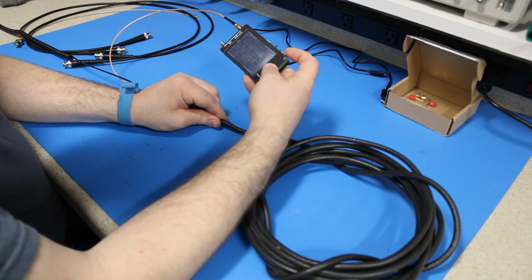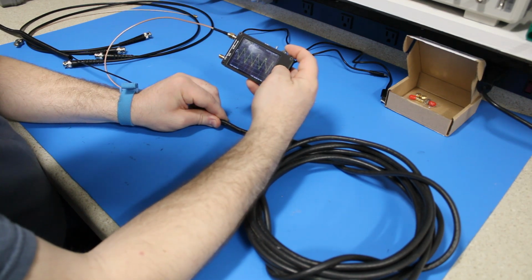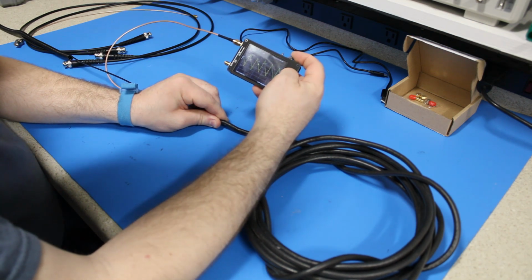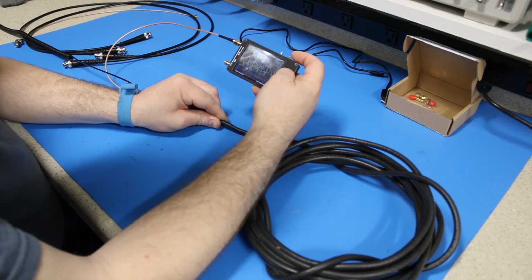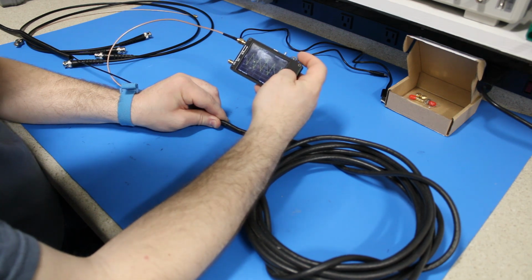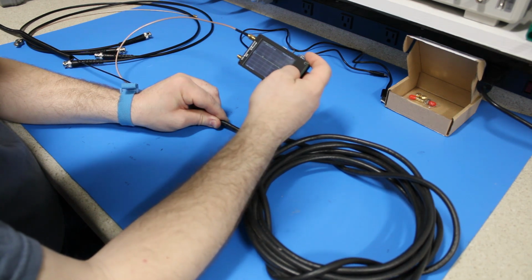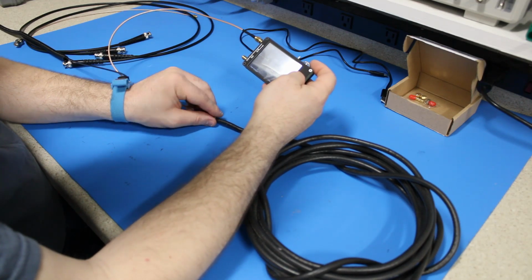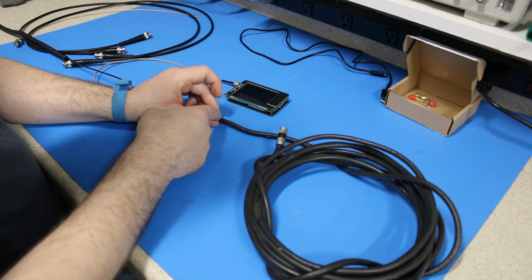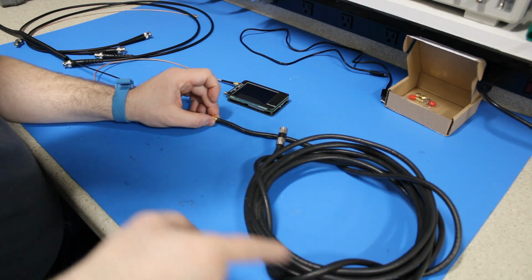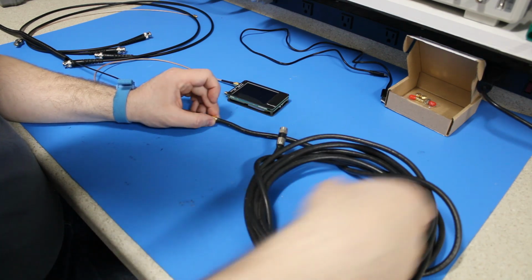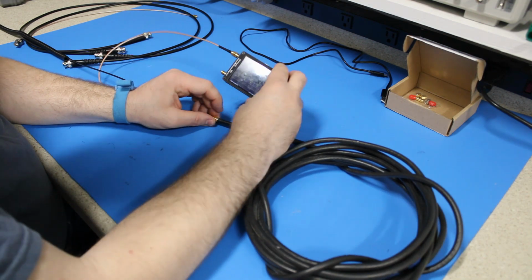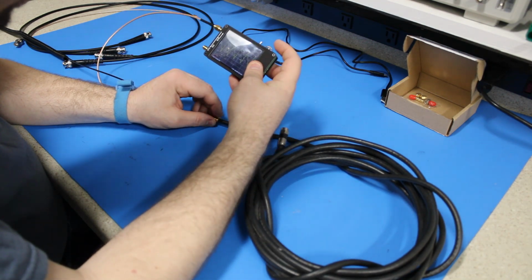Alright, I think we can work with this one. So I'm just going to adjust my marker down. Now remember from the simulation, what we want to do is find the first point at which the phase is equal to 0. That's where we will be when the transmission line's physical length is half of a wavelength, because when the phase is 0 here, the wave has traveled all the way down the line and reflected back to here.